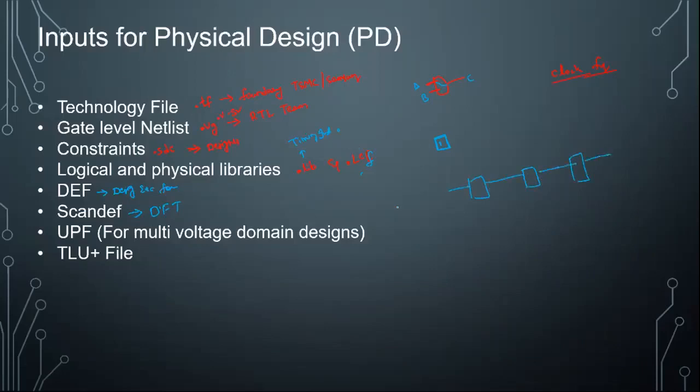So what we will do after fabrication is send one pattern, 1010, so the output also we can expect 1010. If we are not getting the desired output, we can consider something is a failure in our chip. For example, if a physical connection is not there here, I won't get any output, right? Then I can say this is a failed chip, because of the broken net.